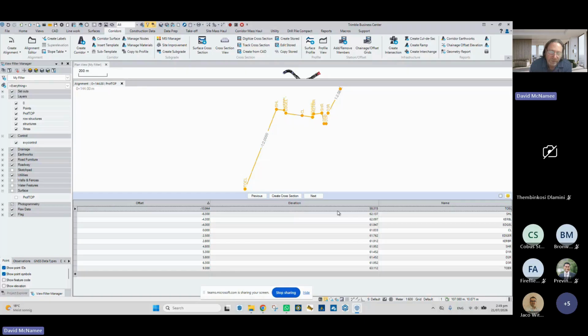You can bring those files into TBC, and then run that IRI file across those as-built surfaces. You can then do all your volume calculations as well. So you can do your as-built against design and see what's going on. But generally it's to run your IRI information. Okay, thank you very much. I hope that answers your question. Yeah, thanks.